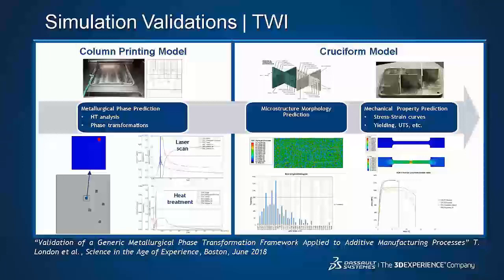We have done this for a cruciform model, in the context of the Ramberg-Osgood plasticity model, to estimate the hardening behavior of as-printed and heat-treated alloys. It is shown that the simulation-predicted dog bone tensile test elastic-plastic behavior matches those from the experiments. For more information, please come to our AM Symposium on June 18th in Boston to listen to the full presentation from TWI.